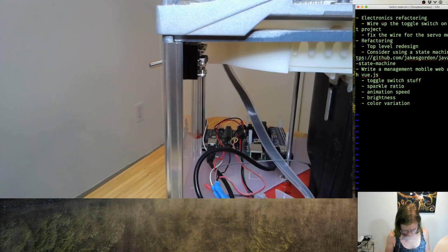So I need a few different wires. I need a good length of them. I'm going to pull out of my little patch wire kit. I always tend to pull a little more wire than I think I'll probably need. And I'm just going to jam these right into the headers in the Arduino because that's what's there now. If I wanted this to actually be serviceable, I'd probably at least make a little perf board shield type thing. Those little perf board Arduino shield kits are kind of nice, so you can swap out that Arduino board in one go instead of futzing around.